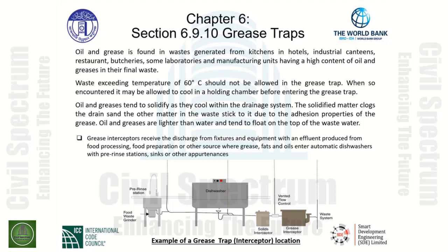We must understand that waste exceeding temperature of 60 degrees Celsius should not be allowed in the grease trap. When so encountered, it may be allowed to cool in a holding chamber before entering the grease trap. This is for the specific function that when we cool down oils, it congeals, it solidifies to a point that it can be captured or drawn off